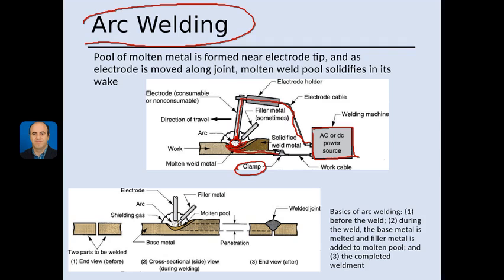The thing is, we have an air gap between the electrode and the workpiece. Air is not conductive, it's an insulator, so it will block the electron movement. There are some tricks to make the air conductive. It's called plasma. So we convert the air into plasma.